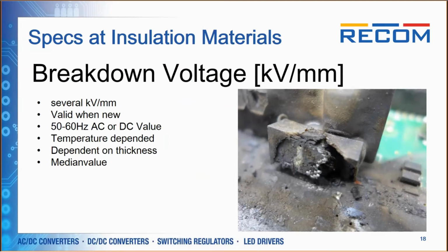This is given in several kV per millimeter, and is only valid when new. It's a 50-60 Hertz value or DC value, also temperature dependent and dependent on thickness. And what is also very important: this is not the maximum or minimum value, it's a median value. So you can have some which are even below that.